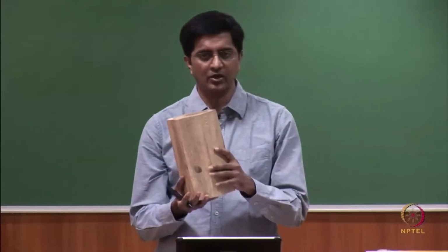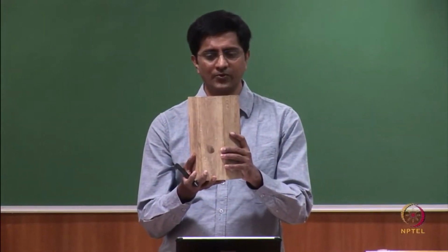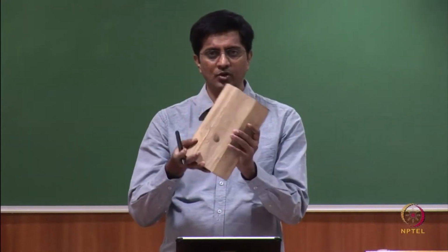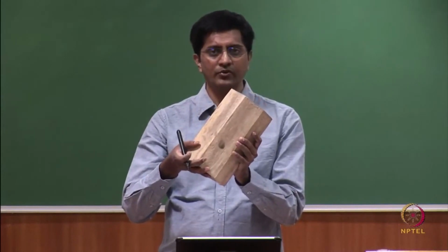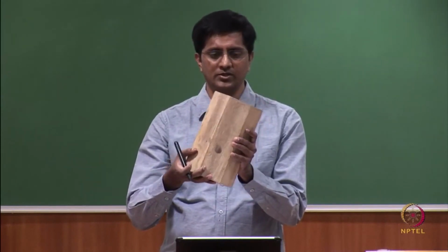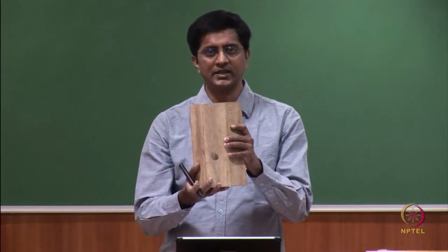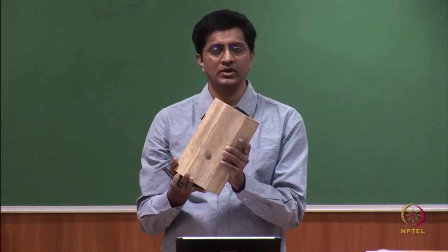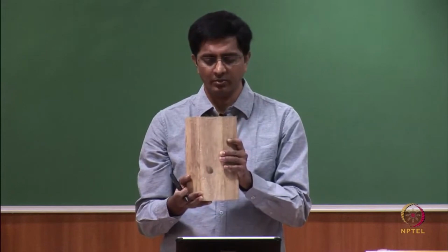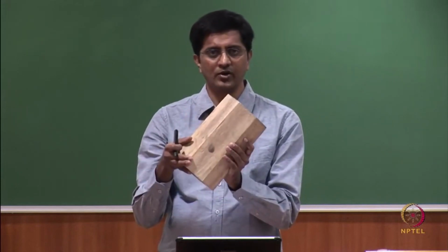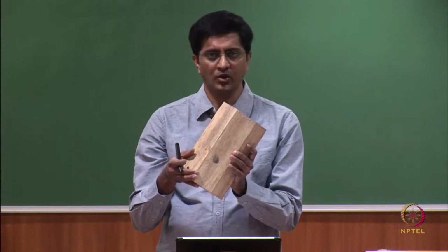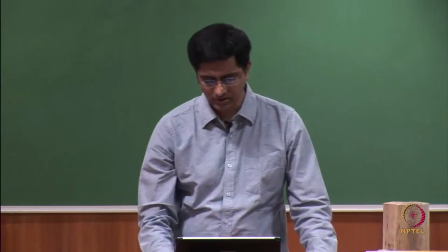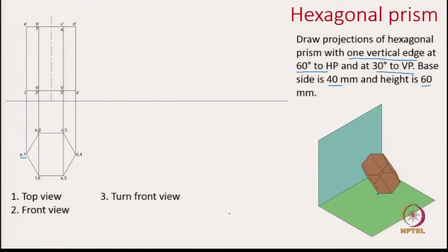So, again I am bringing the object. So, this is the step 1 and this is step 2. So, from step 1 before rotation to after rotation, will the front view remain the same or the top view remain the same? We see that this hexagon in the top view now becomes a squeezed hexagon. It is not the same, it does not retain the true shape, but the front view before and after rotation retains the same shape. The only difference is the shape is rotated. So, now let us capture the front view, turn front view.